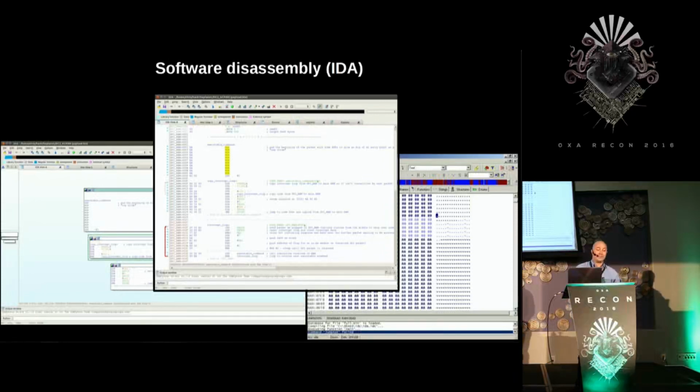Later, I remembered looking at an older access controller from the same manufacturer, which was used in a previous system, VideoCipher 2+. It's an ancestor of DigiCipher. On this older chip, there was actually a copyright notice from WDC, who licenses the 6502 core IP, visible directly on the chip die under microscope. So this would have been a good clue to the CPU architecture if I'd actually noticed it earlier. For the disassembly, I used IDA. It includes support for 6502. It's very powerful.